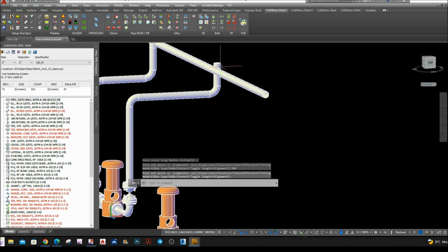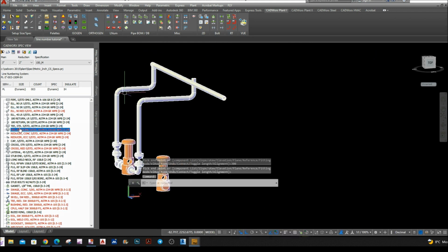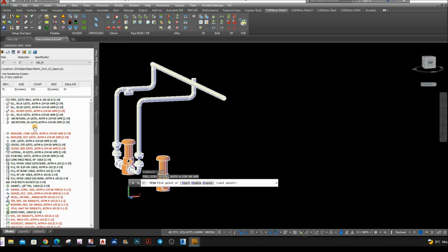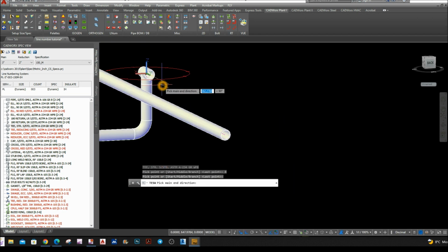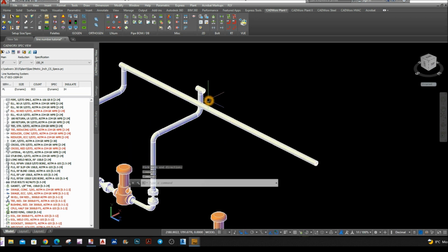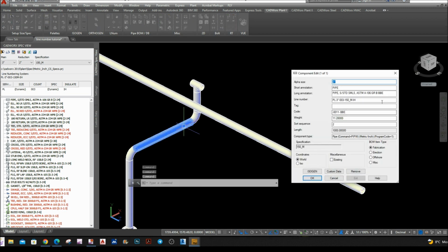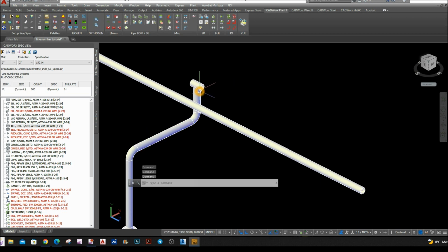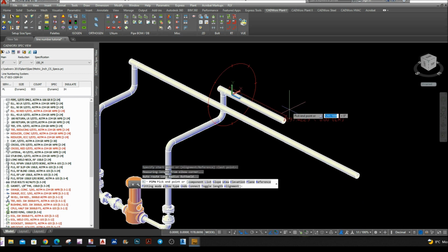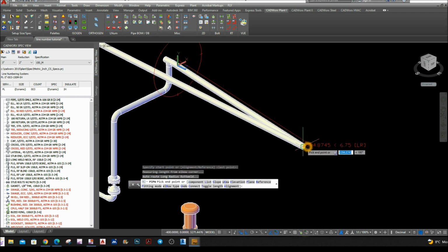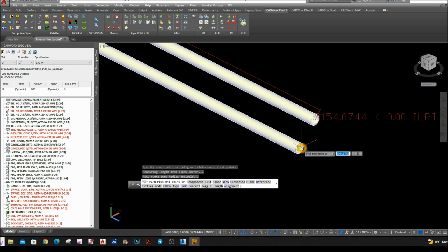Enter again, and attach a T and click branch. Now I'm holding the end of the branch and attach it to this in point and assign direction. So along the y-axis, just click. Now, this one is 003, and I'm gonna continue on. So attach a pipe from this in point, and I want that pipe's length to be the same as the end here.